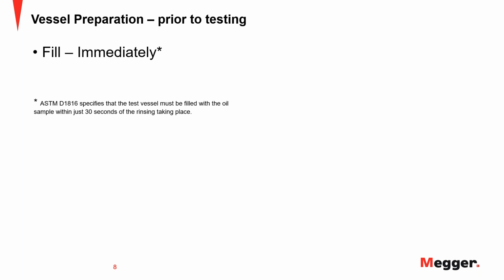Okay, and then as soon as you've done the rinsing, you need to make sure that you fill with the sample oil as quickly as possible. So immediately, you need to make sure that this is done in order to minimize any contact with air during the time between rinsing and filling for the test. ASTM D1816 specifies that this should typically take less than 30 seconds in order to minimize that contact with the air.